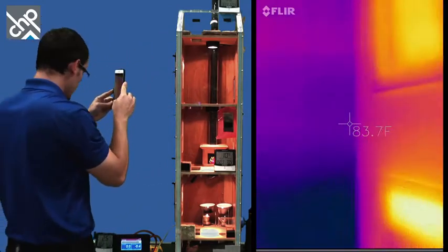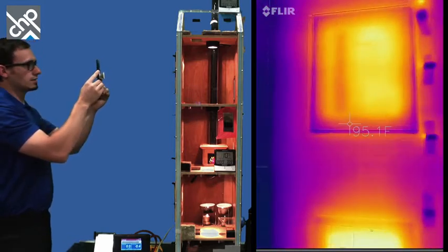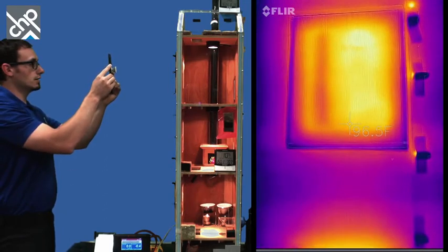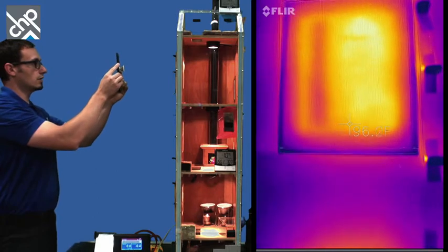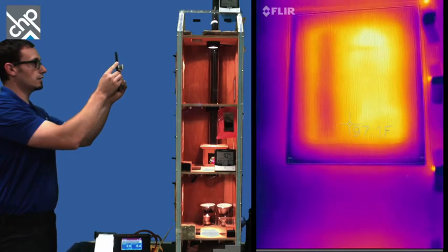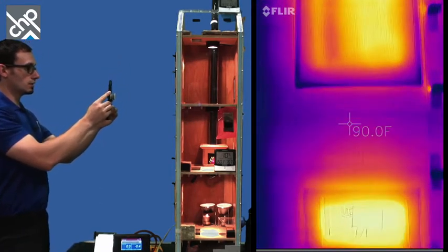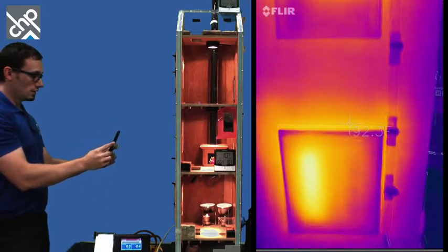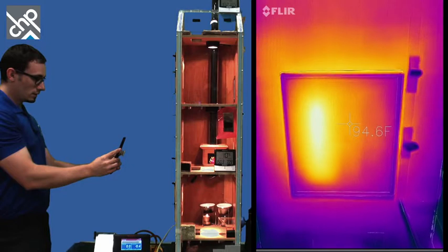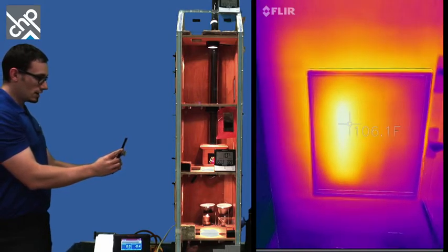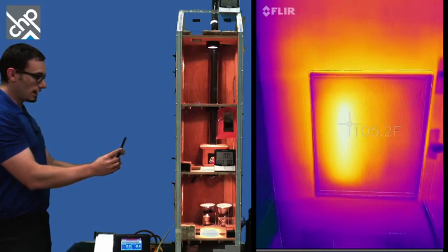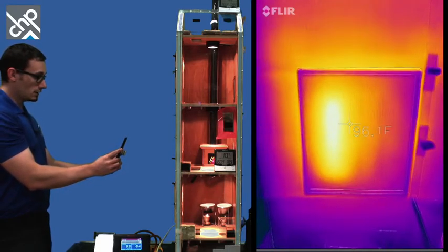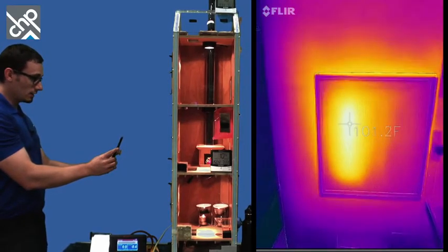And then if I pan over here to the side of my house, I can see my wall assemblies. Each of these wall assemblies has three cavities, and you guys can probably see one of those cavities looks a little bit different than the others. I've got another wall section a little further down here. This is a window, a window with some insulation in there. That one's clear. But on my other framed wall, something else is going on. That hot surface temperature is going to show me a lack of something in this wall. Any guesses as to what that might be? Insulation. Yeah, my insulation is missing from one of these cavities.